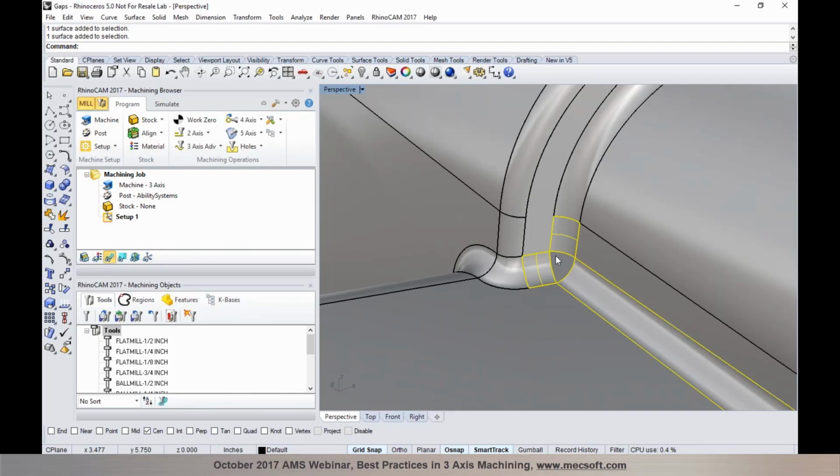But even in cases where you have small gaps or small overlaps, what you're going to notice is tool marks. Because of the gaps, the cutter is just going to dip in slightly and come back out if the cutter is large enough that it doesn't fall in. So at the end of the machining, you're going to see tool marks on the surface. That's why Uday is suggesting that solid models with edge-matched surfaces, or polysurfaces with edge-matched surfaces, are the most important formats if you're very concerned about surface finish. Thanks, Uday. Thank you, Joe.